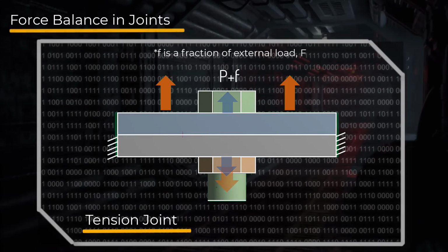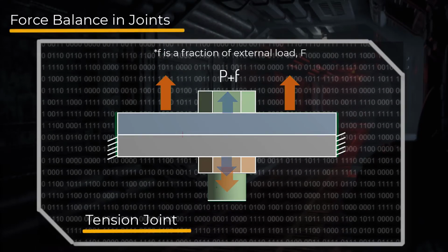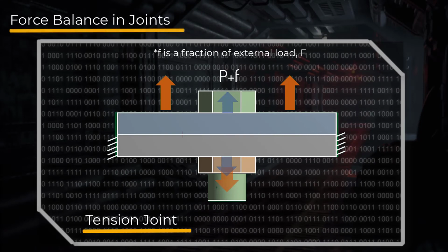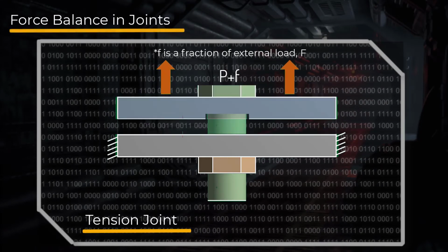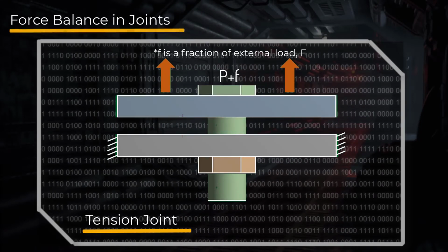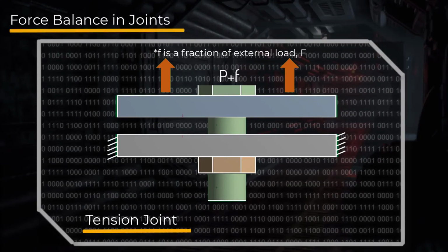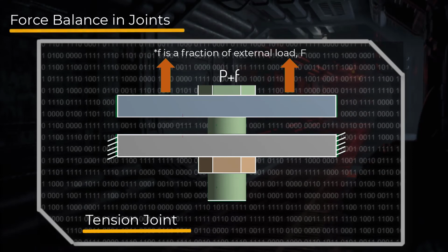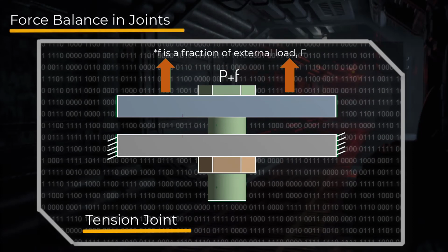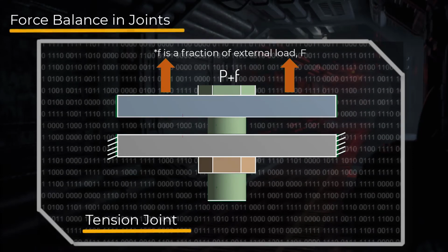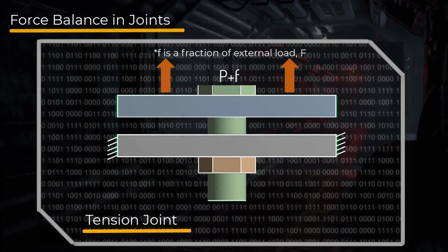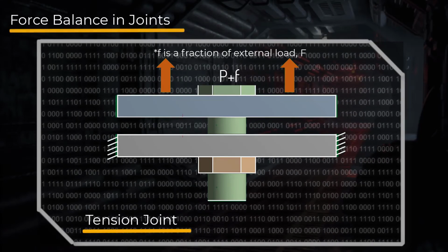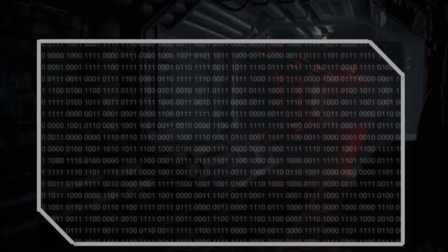In case there is a failure in the bolt, such as failure of threads, or if the shank experiences excess plastic deformation, then the forces are not adequately transferred to generate this reaction force. So, the external load is no longer balanced. As a result, the system is not in a static state anymore, and at this point, it's considered to have failed to support the external load.